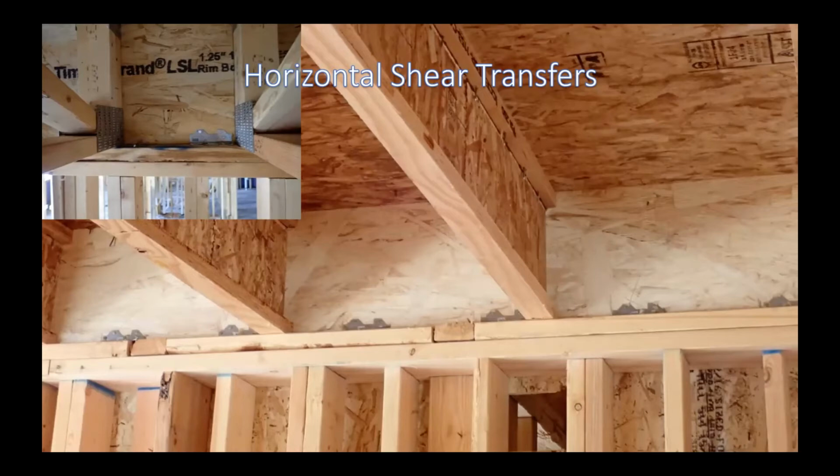So the forces are quite big. A couple of skew nails to fix the truss down, say, to the top plate is not enough to transfer the shear forces. They want full transfer of the forces from the upper floor diaphragm down to the lower shear walls.